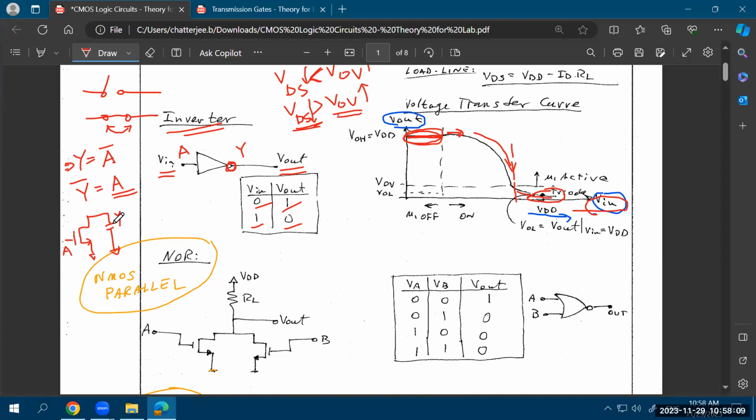So generally in digital circuits, the load is a capacitor, not a resistor. And that is because all MOSFETs will have some parasitic capacitances. So if there is a MOSFET following this particular device, then you'll see a parasitic capacitive load. You will not have a resistive load. You will see a capacitive load, and that will be defined by the parasitics of the device. In most cases, you can also have a physical capacitance, but that's rare. Okay, so that's how we are designing a part of the circuit.